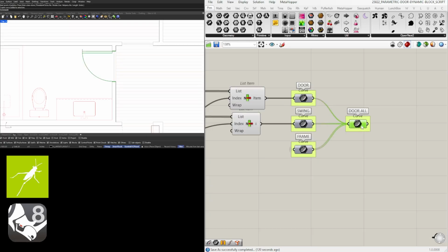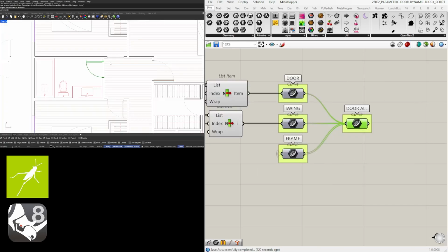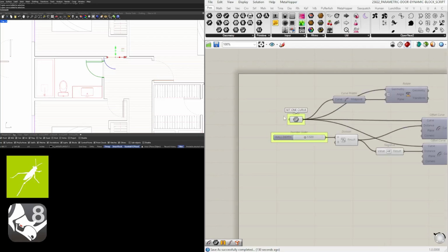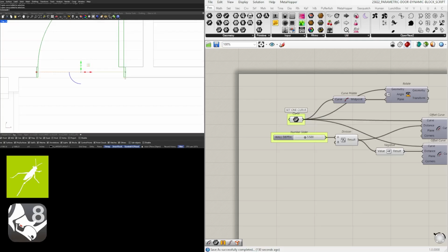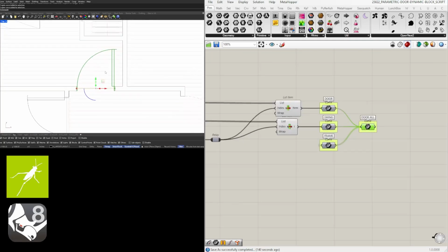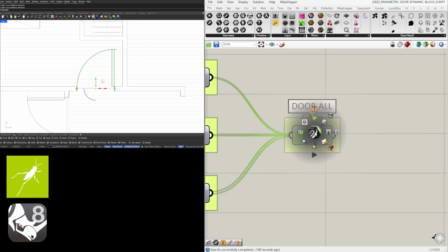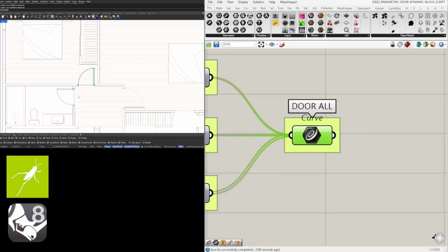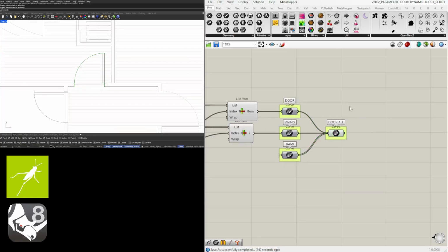And then we can take this and bake it. Then we can go to this one. Go to set one curve. We know that this is a 3.5 wall, and then we can pick the rotation or where it's located and then bake it. So notice that now that's all I had to do, and now I can just hide the script here.